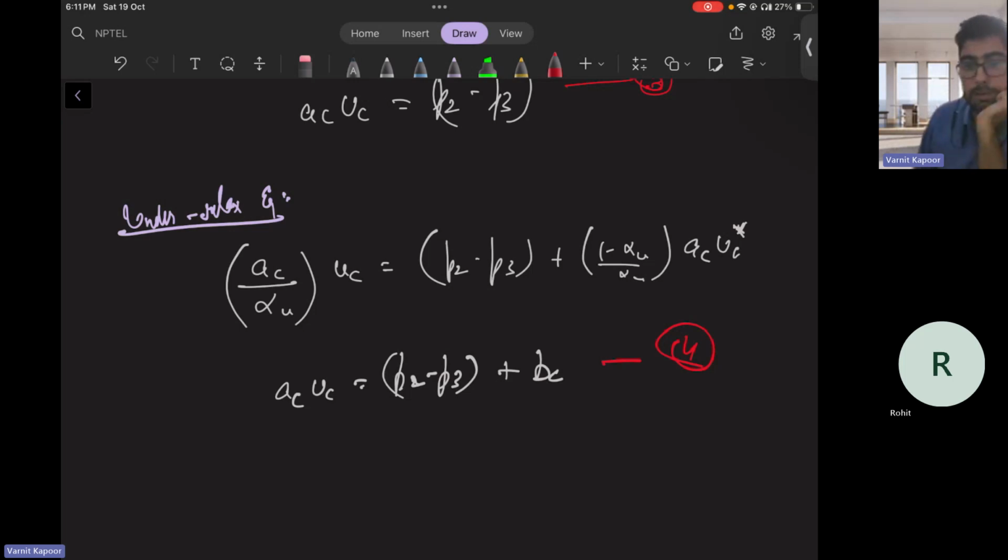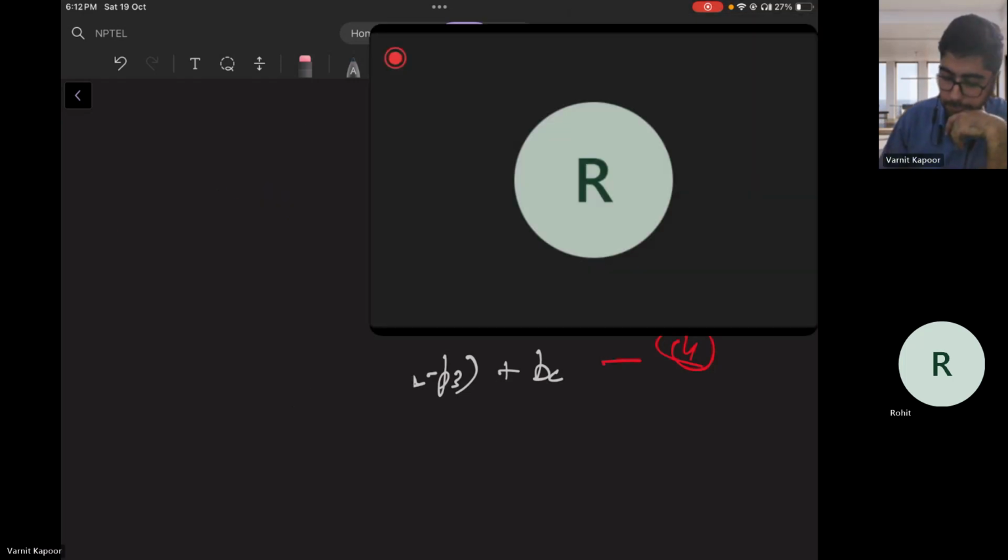Now one more thing that we have to do different from what we have done in the staggered mesh is basically the boundary condition. U1 and U3 are given, but we do not know the pressures for these locations. They are unknown. But in order to know them, we need relevant equations. These are basically the same governing equations, which control how pressure and velocity are related.